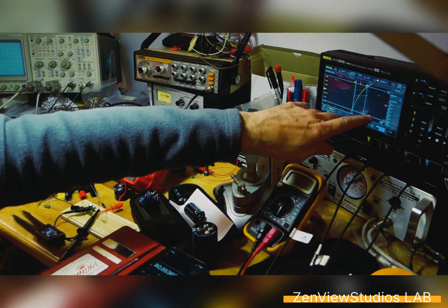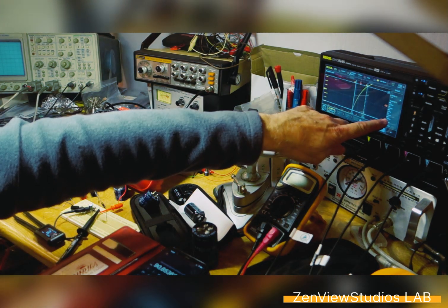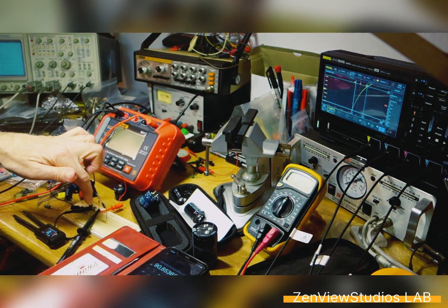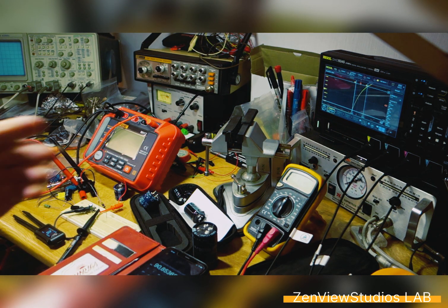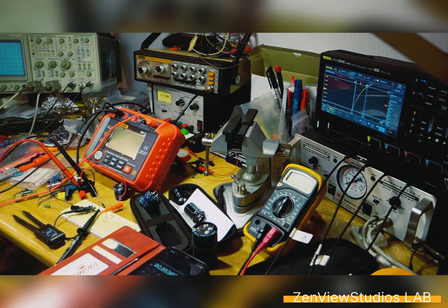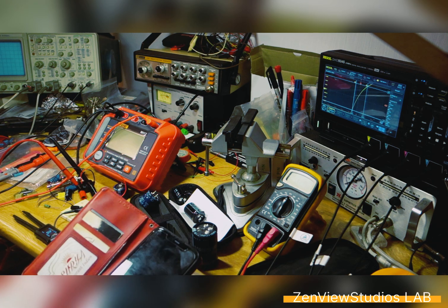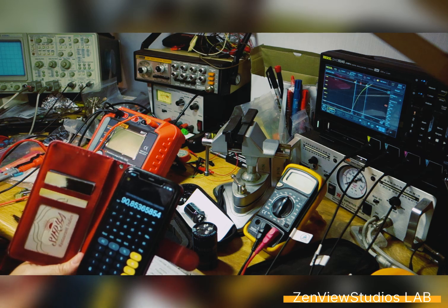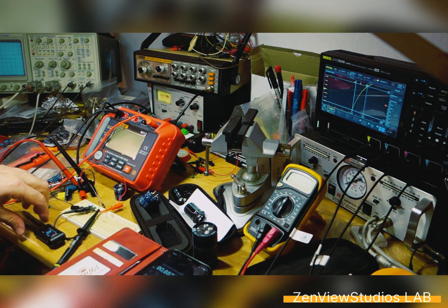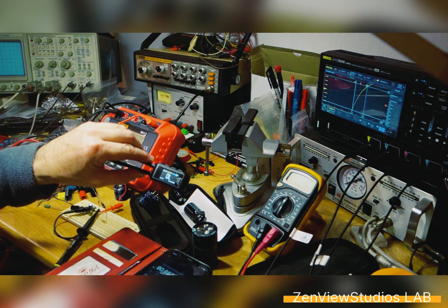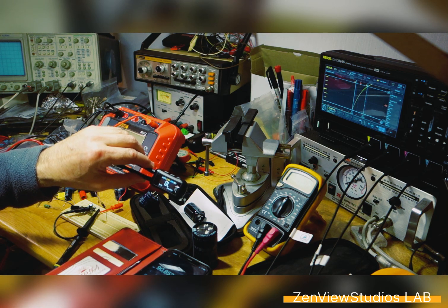Voila. And this is where we read the 7.45 millisecond, and I have 82 ohms here, and if you plug in the numbers, you get 90.85 microfarad. That's the result you get from that. So another way to check whether this little gizmo is giving you some proper idea.